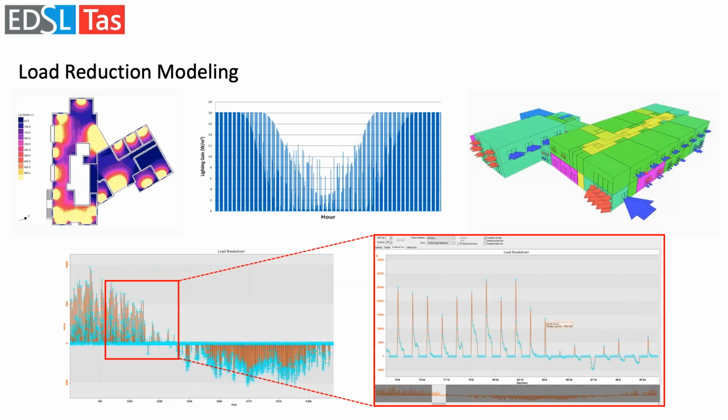Another thing after doing that, once you've done those early concept daylighting model analyses, is being able to integrate that into lighting controls. So doing daylight dimming. You can see here the interior lighting load. You can see every week in this office, because the weekends are the gaps, how that dips down for all the zones in the building at different levels through the year with that daylighting control. And basically this block would be filled in without the dimming control.